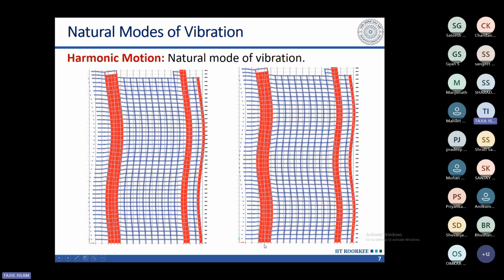Then come back to this one. Let us consider this is the vertical axis. If I look at this point here, it is changing direction. Then here again it is changing direction, and here again it is changing direction. So the intersection is happening three times. So this is our fourth mode shape, and so on. I have considered only these four for demonstration here. Similarly, there will be a lot of other mode shapes depending on the total number of mode shapes available in your structure.